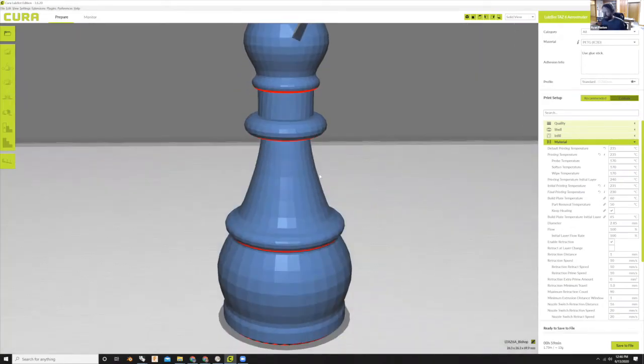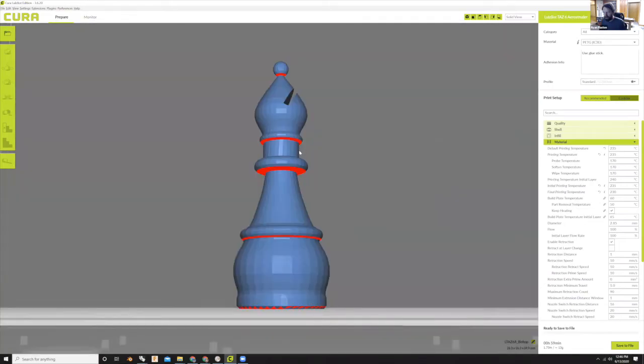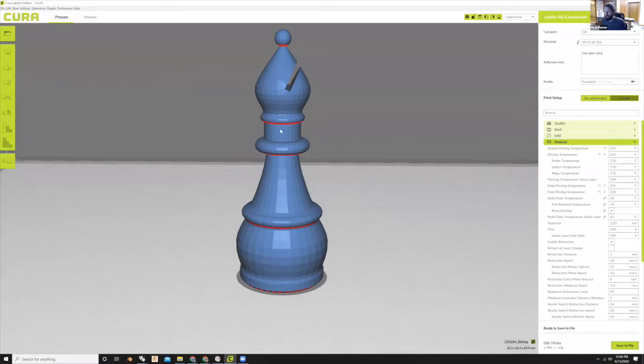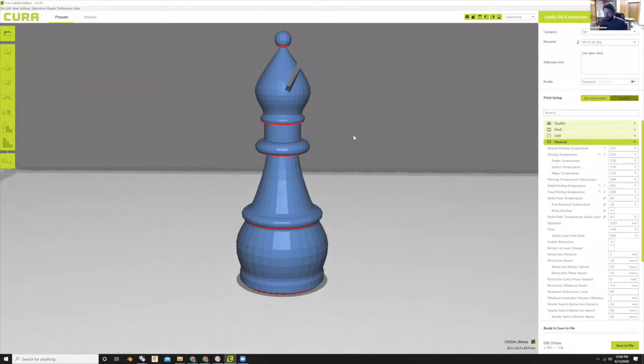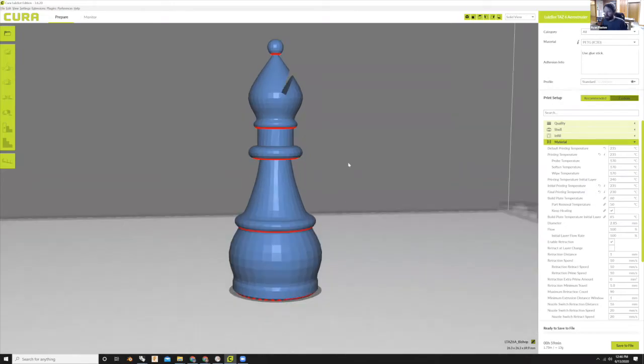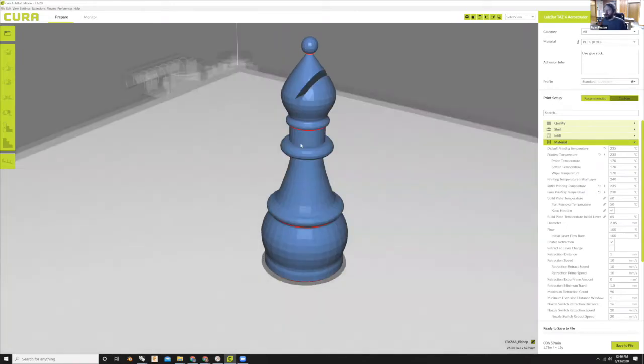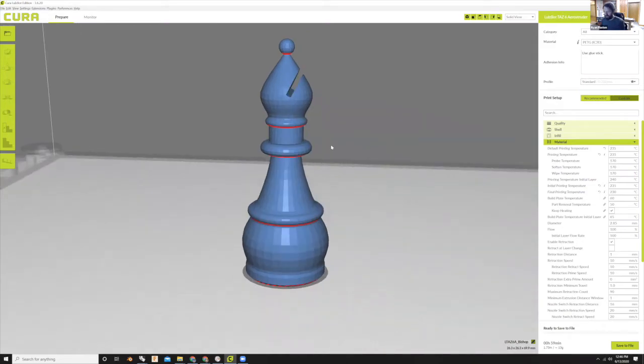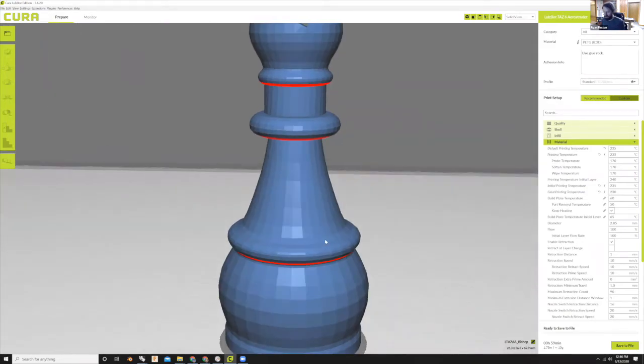I highly recommend not using supports. If you can design appropriately, you'll have much better print results. Supports sometimes are necessary. Like if you're doing sculptural objects, sometimes you just need it. But if you can design around it, you'll get better results. So I printed this object without any supports and actually didn't change any geometry.